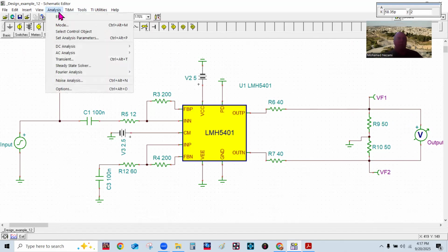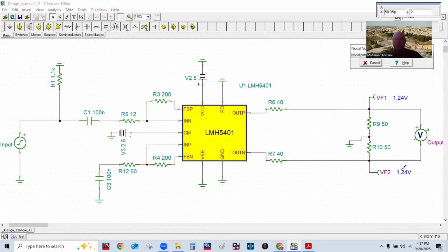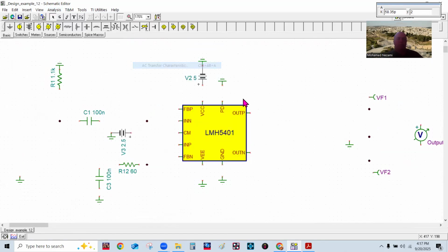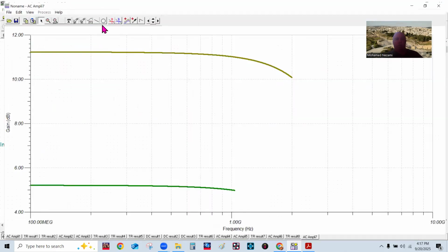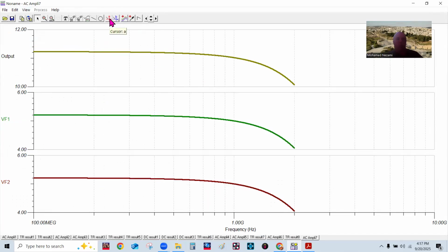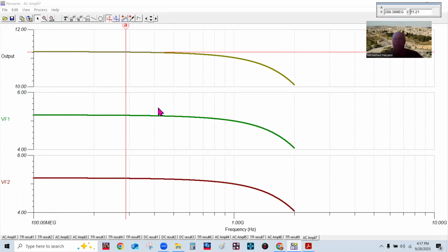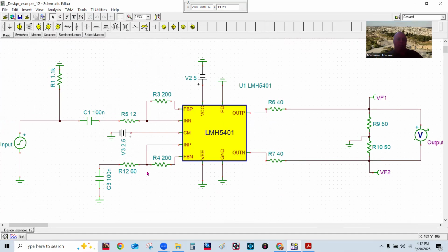This is modeling the differential load of the ADC. So let's see, DC-wise, what do we get on this guy here. You can see it's fully balanced. And then AC-wise, we can look at the transfer function. You can see this is a real nice device. It goes all the way past a gigahertz. You look at the flat region, this is about a gain of 10 right now, 12 dB.